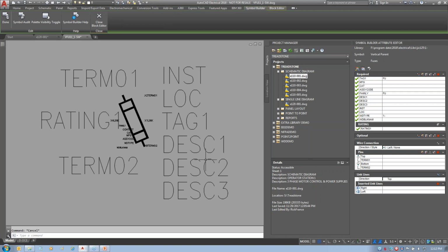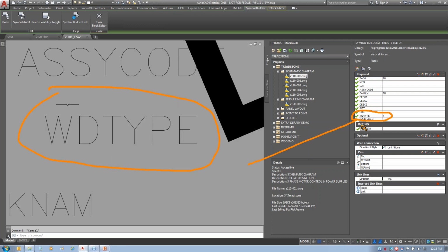When it's in a drawing and it's set to a value of 1-, that tells the software that this is a single line, one line component. I can't remember all of them, but there's one for pneumatic, I think that's P and U or something like that. I can't remember off the top of my head. It would be a pneumatic symbol. There's one for hydraulics, HYD, I believe. I use P2P for point-to-point symbols. So this attribute is valuable to tell the software that this is not a normal ladder diagram schematic symbol.